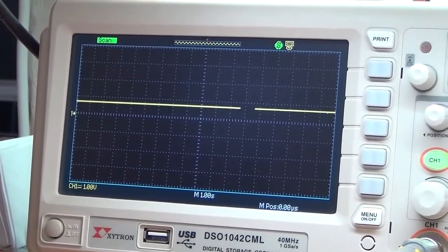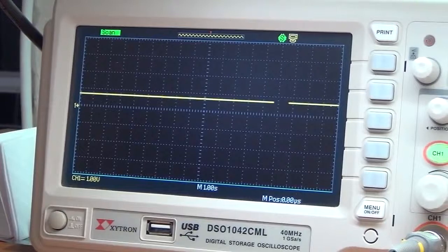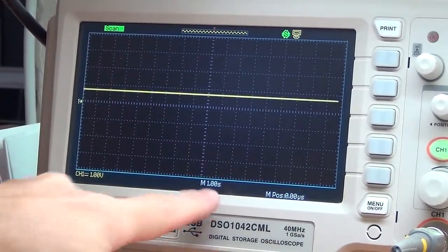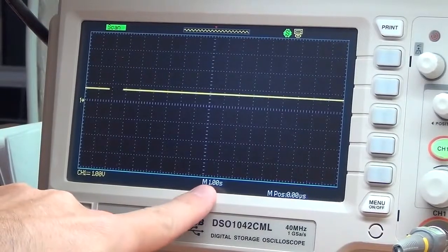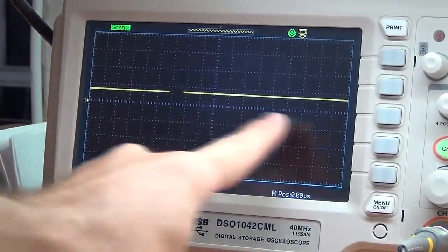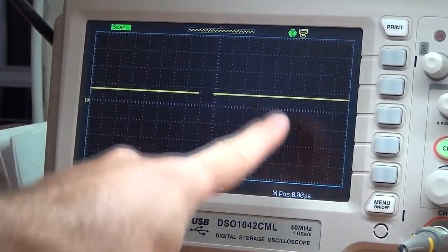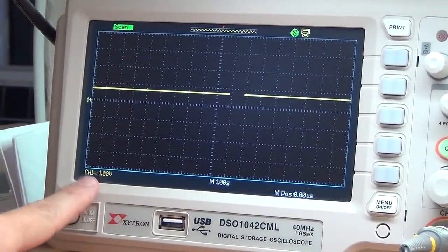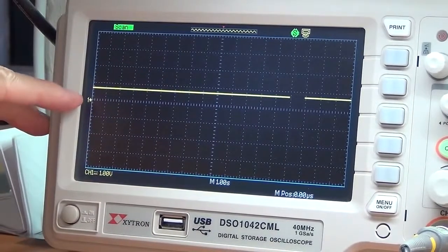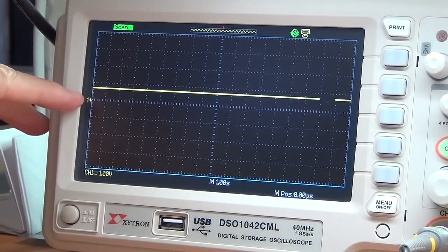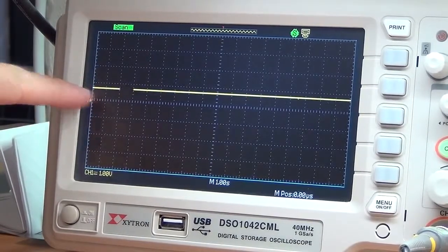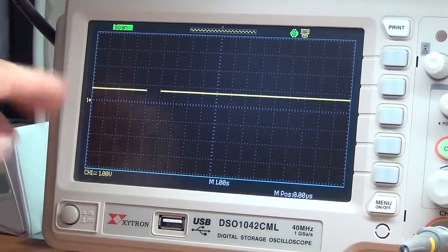Now the oscilloscope is in a kind of scan mode. It's not being triggered by a high frequency signal coming in. I've got my time base set to 1 second per division. So I can show quite a few seconds. You can actually see the scan going across, how slowly it goes across, and I've got it set to 1 volt. So my reference is set at the 0 line. So as you can see, we're just under 1 volt of charge in the capacitor currently.